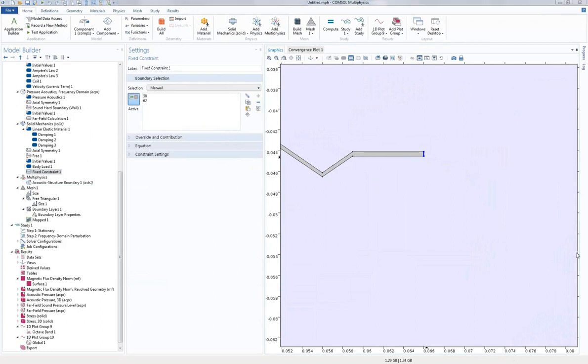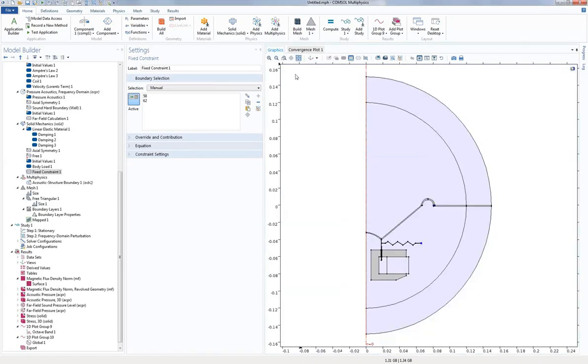So what's next? Let's see. Maybe you should mention that the 3D plots are extrapolated 2D data with only radial variation but no circumferential data. That is indeed true. This is an axisymmetric model, and right now the way I've set it up, per default, it assumes that everything is invariant with the phi direction, the out of plane direction right here. You can also model in 3D, of course. That takes a longer time to solve, but otherwise the principle is the same.